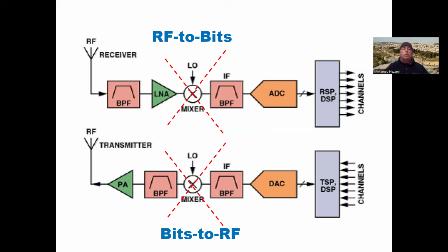But beyond that, of course, you really have to have a frequency translation so you can bring the frequency down and utilize the commercially available ADCs, analog to digital converters. Now, there are some exotic products out there that digitize at rates from about 20 megasamples per second all the way to 60 gigasamples per second. But of course, those are very expensive, and they're not really geared toward commercial use.